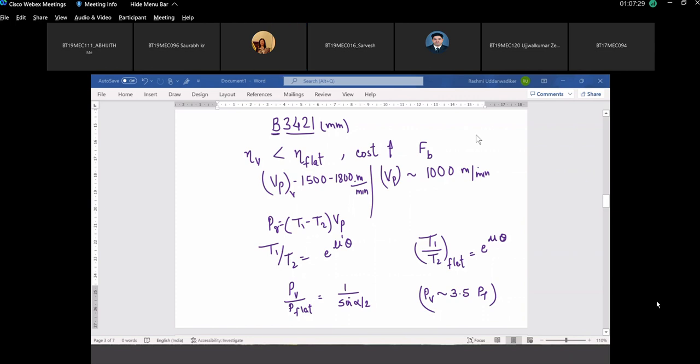Also, the flexibility of V belt goes down. Here we lose power because of the bending stress also. Due to its thickness, you have seen its cross section is trapezium. Because of this trapezoidal cross section, the thickness has to be more than the flat belt. Because of this, there is a layer below the neutral axis and a layer above the neutral axis, undergoing tension and compression.